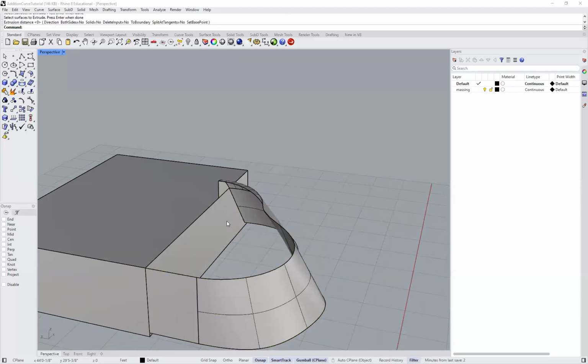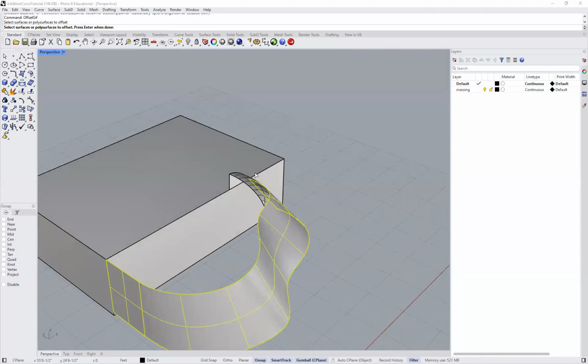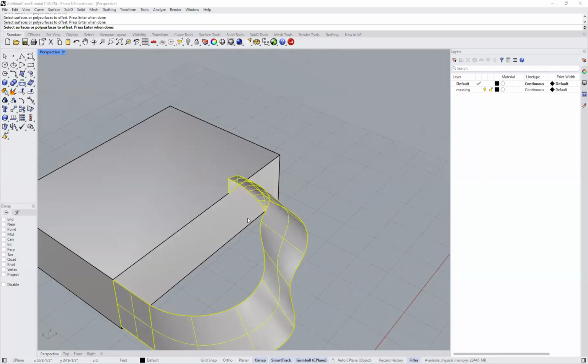Sorry, I take that back. It's not extrude, it's offset surface. If you saw right now, extrude will extrude it kind of up and down, and you'll notice that that's not really what we wanted. What I want is offset surface. So I'll select that surface, and this surface.